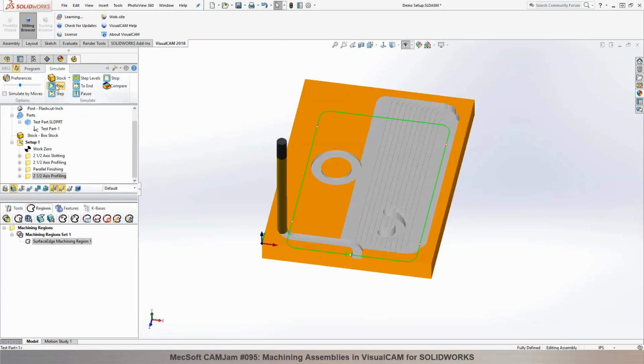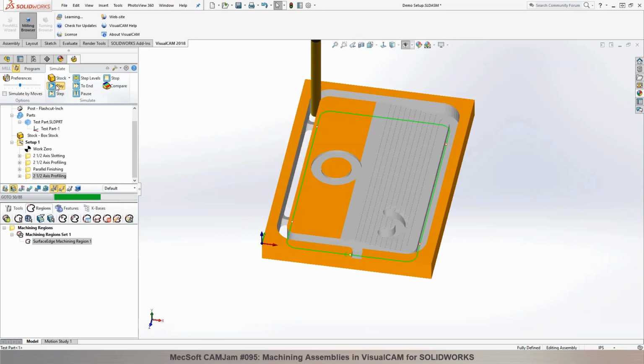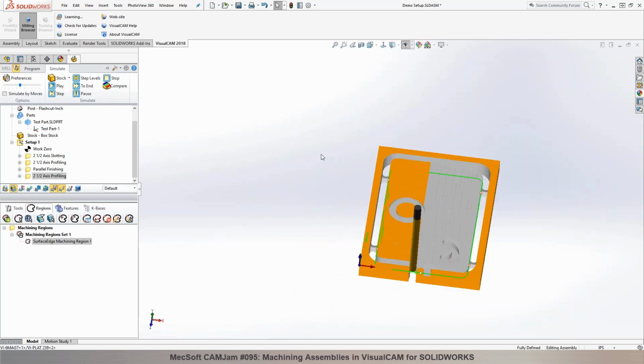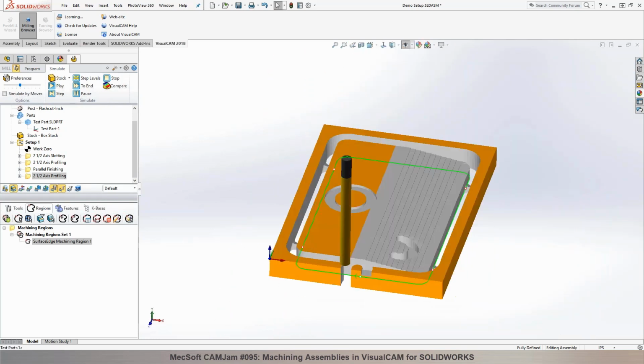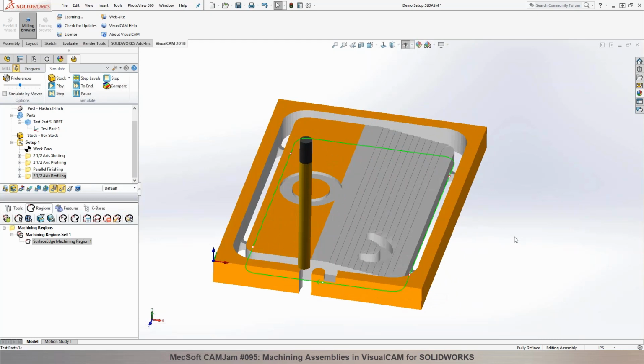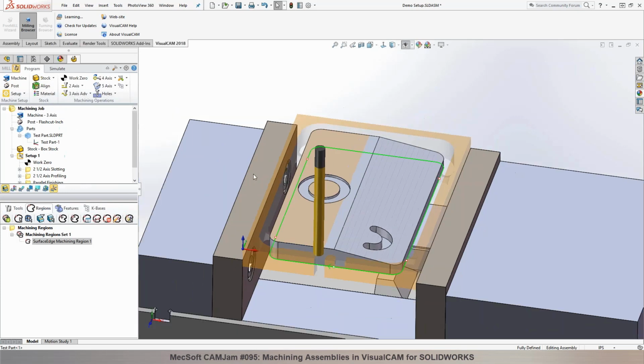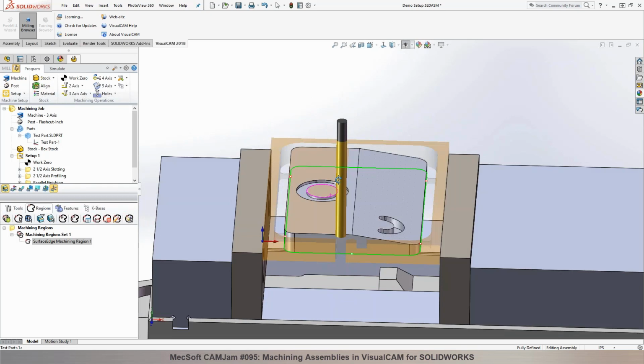So if I go back and run a verification, you'll see that it does a triangular bridge where it kind of ramps down and ramps up. And you can control the bridge length and the height. In some cases, users like to leave a little bit of material at the bottom, so not cut all the way through. So you can leave an onion skin if you don't want to leave bridges and tabs, so you can basically easily break it up. So in this particular case, we did not have to specify, or in any of these, we can validate it by looking at it here.